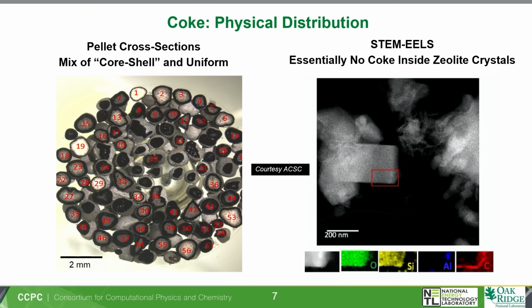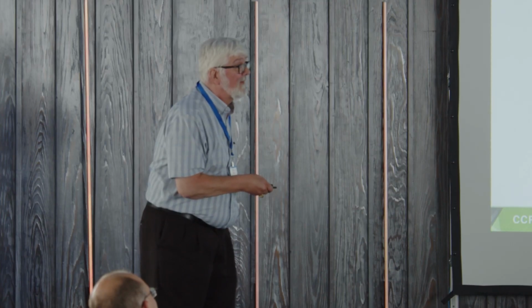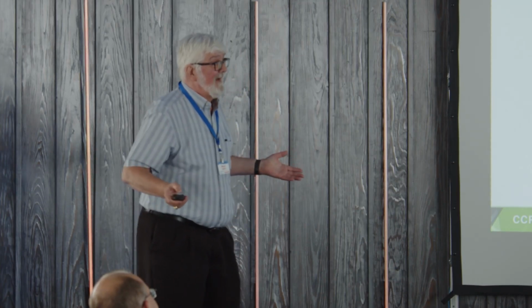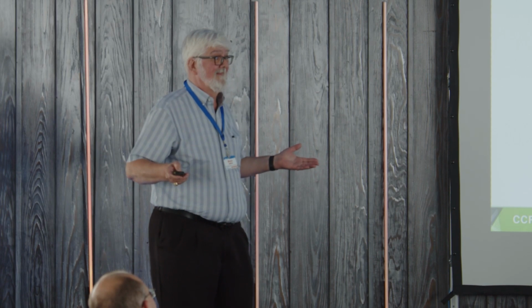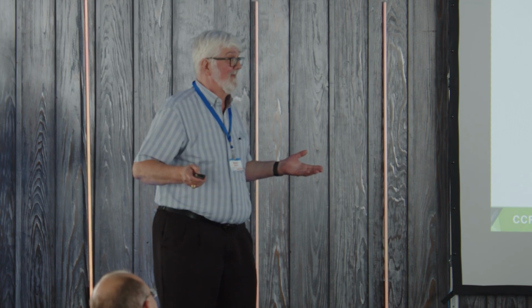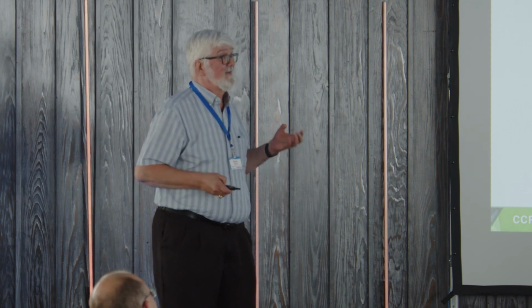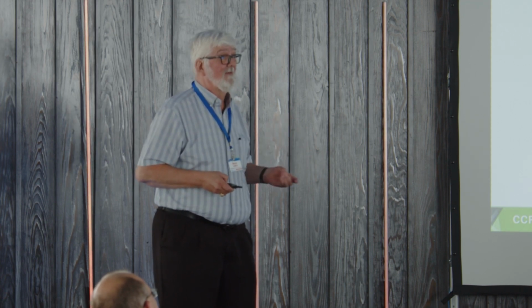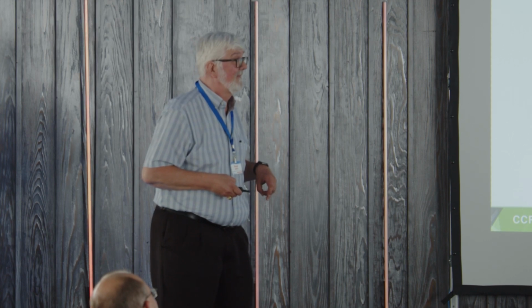And the other thing that we learned from this, and this I knew from my FCC days, there's no coke inside the zeolite crystals. With ZSM5, you can't get anything bigger than a 2-ring aromatic compound inside those micropores. You don't expect coke inside the pores. That's important. It teaches us which pores we actually want to model to do this deconvolution.